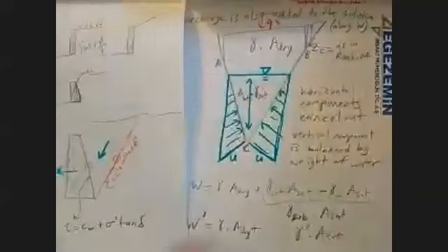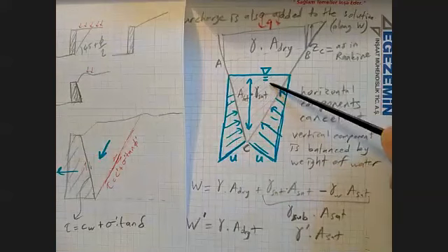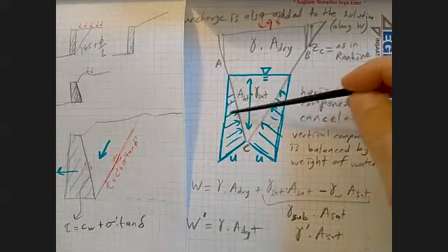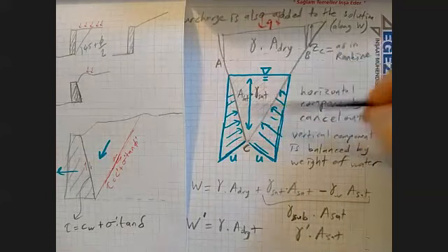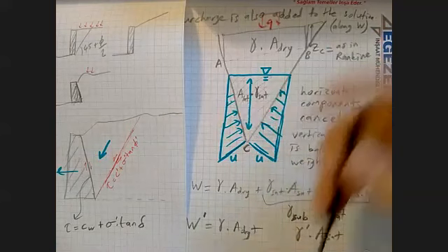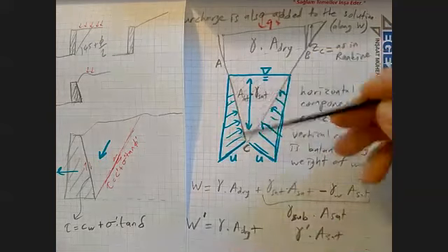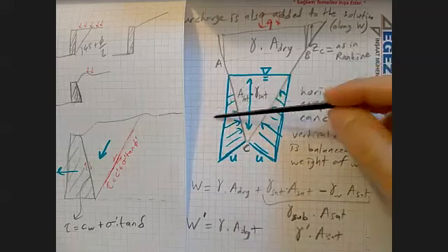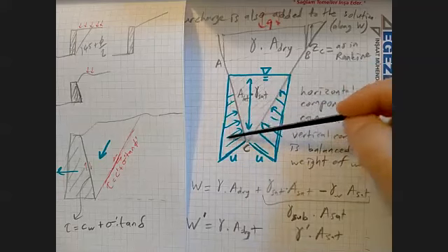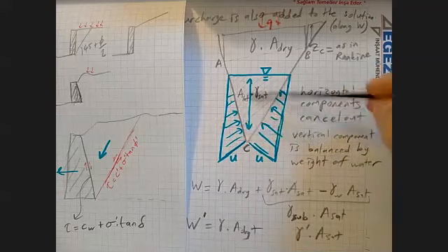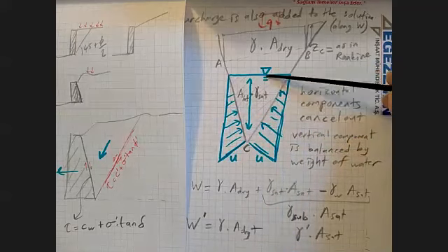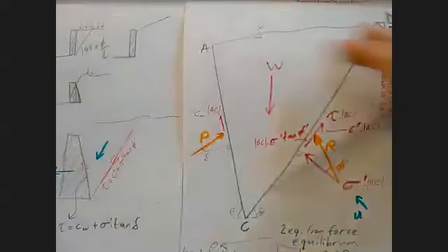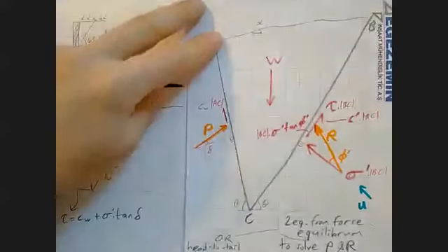By the way, you might not know the water, but the common practice is to drill holes into such walls. Such gravity walls usually have holes. You might see them in retaining walls of gardens, the small scale retaining walls, or retaining walls on the roadsides. They are called weep holes. So when you drill weep holes, you are opening this water to the atmosphere. So you are effectively lowering the water level to where you have the lowest holes, for example. So somehow you can manipulate the water pressures and you can know them.